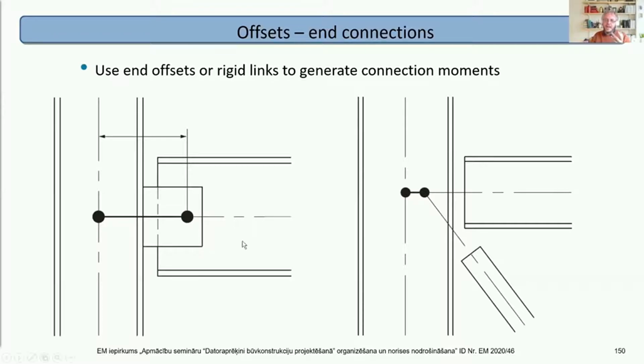Also, watch out that I've shown the beam on one side of the column. There could well be beams on both sides of the column. Uniform loading will give you no bending moment in the column, but patch loading, partial loading, will give you some moments. So how you load the model might be significant. Alternatively, load everything to the center line and then add in some notional moments in a separate calculation. If you're calculating the section sizes directly in the FE model, watch out for those eccentric moments.